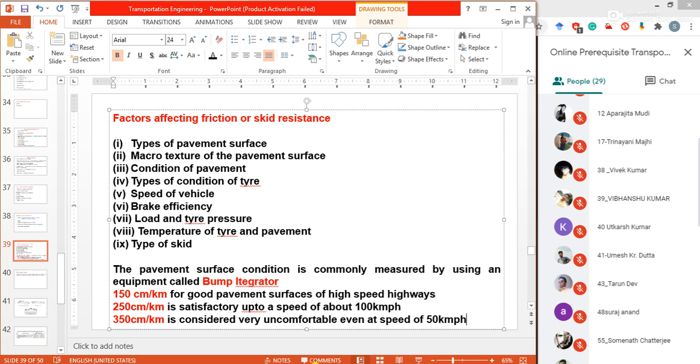The unevenness or undulations on pavement surface may be caused by various factors, such as number 1, inadequate or improper compaction of the fill, subgrade and pavement layers, unscientific construction practices including the use of boulder stones and bricks as soling course over loose subgrade soil, use of inferior pavement materials, improper surface and subsurface drainage, use of improper construction machinery, poor maintenance practices, and localized failures due to combination of causes. So lots of factors are involved in unevenness.